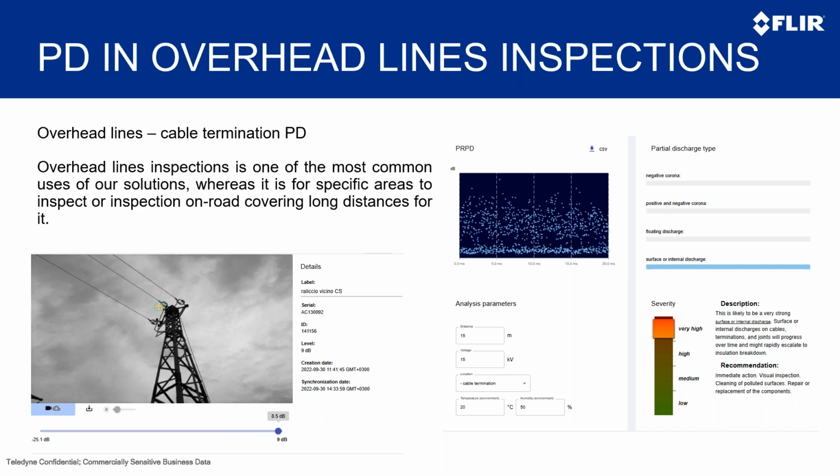You will get analytics, and after you have got the analytics, you will get an evaluation of the partial discharge, its typification. In this case, it was surface or internal discharge, and the severity level. As you can see in the low right corner of the screen, we have the severity assessment. This is displayed in the camera, so you will have direct access to this information in the camera.